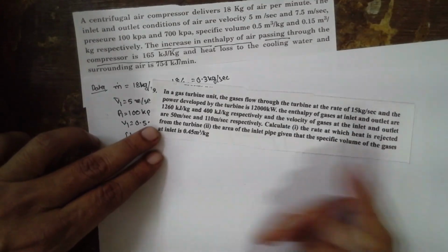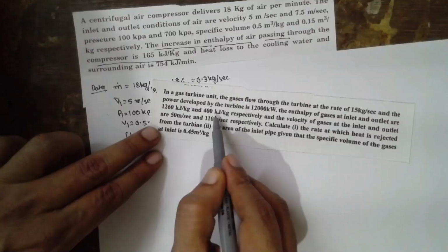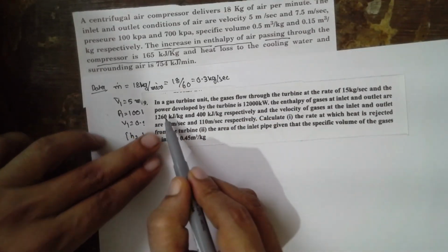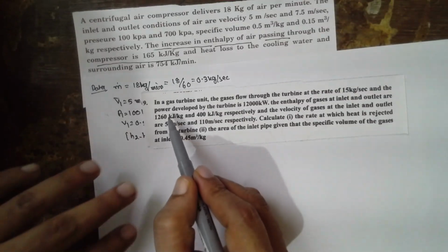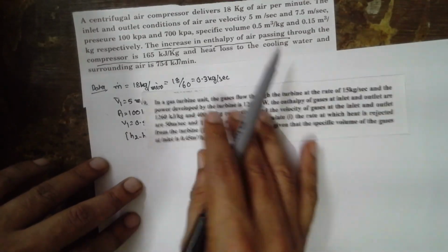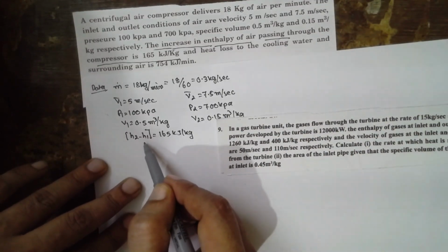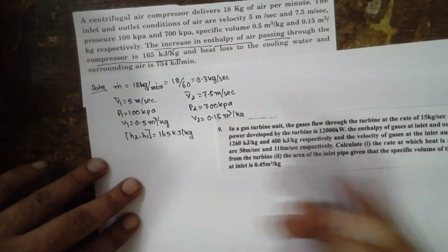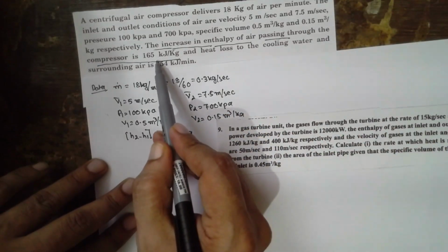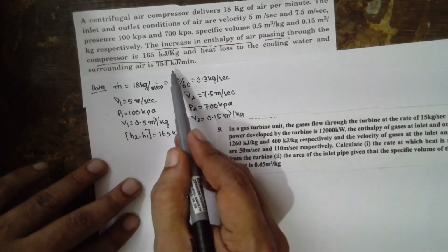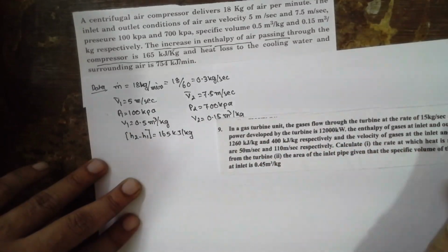In this way they will express it. There are 2 enthalpies they are going to mention here. Normally they will be in terms of 4 digits. If they have given 3 digits, it indicates that it is a combination of H2 minus H1. If they have a single value, they have mentioned it in terms of enthalpy difference, therefore you have to consider H2 minus H1. If there are 2 values, you can consider one to be H1 and the other to be H2.